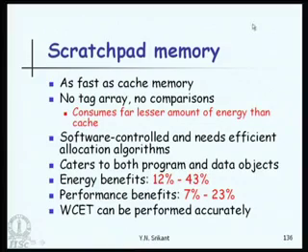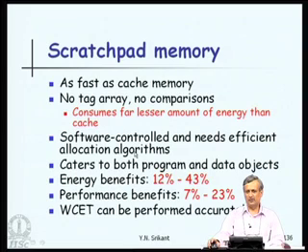But if we have a very large number of registers, the scratch pad memory elements, say thousands, some kilobytes, say 10 kilobytes, 20 kilobytes, it is not possible to name them, and the programmer cannot even think of using these names in the program. So, that is the difference between a cache memory, a register set and a scratch pad memory.